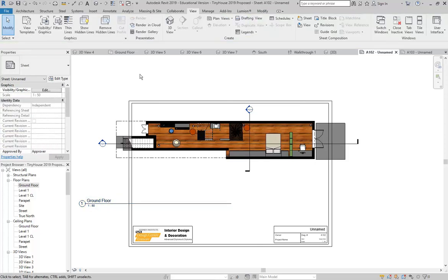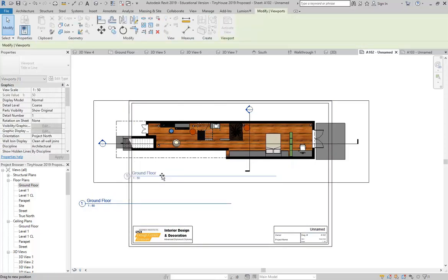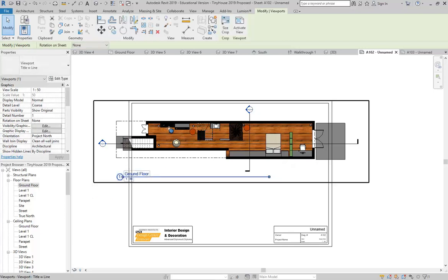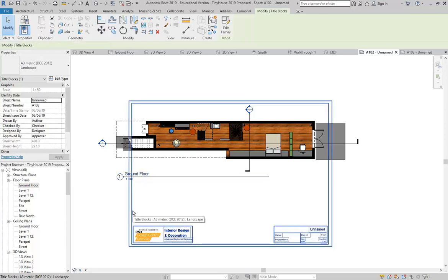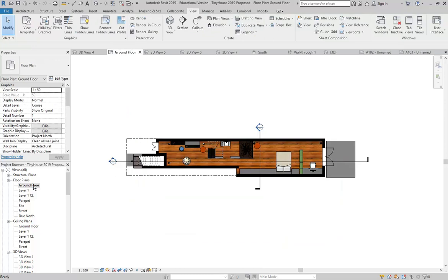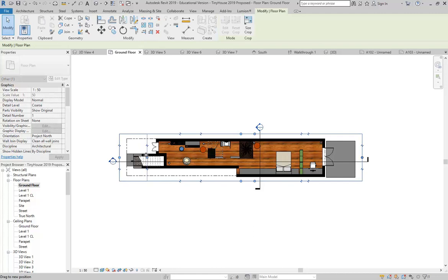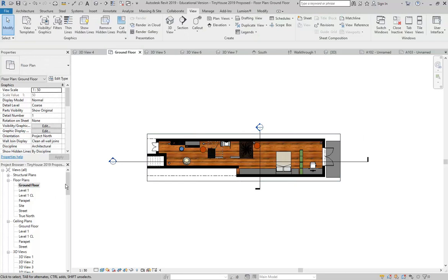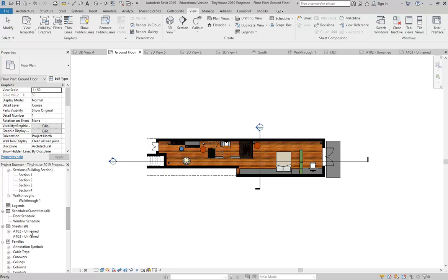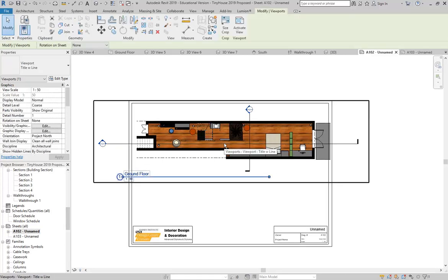And this is something, it's a really handy thing actually to work out the right page size and also the right scale for the space or the building that you're working on. So if I really wanted this to be 1 to 50, I've got a couple of options. I can either make the page size bigger, I could make it A2, or I can go and crop that view a bit more. We don't really need to see all of the stairs there, and I can bring it in so I don't see all of the backyard, and then I'll hide the crop region again, and then on the page, it's of course got those changes, and then I can just make it fit.